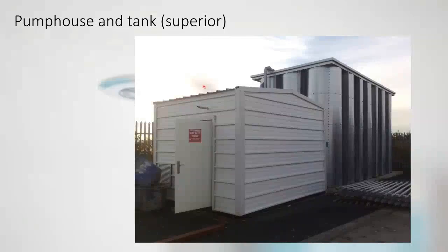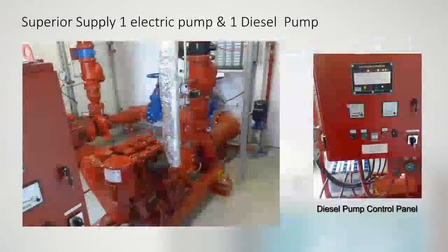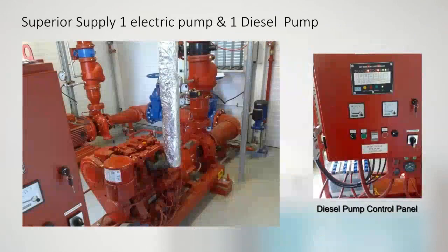Okay. This here is a diesel pump house. There you go, you've got the exhaust pipe here, and that's a Franklin Hodge space saver tank. Looks something like this inside, so you've got a diesel pump here, an electric pump here. Always lag the exhaust pipe, you don't want to get burned. Okay, that's an SPP pump. You've got the panel at the back here.